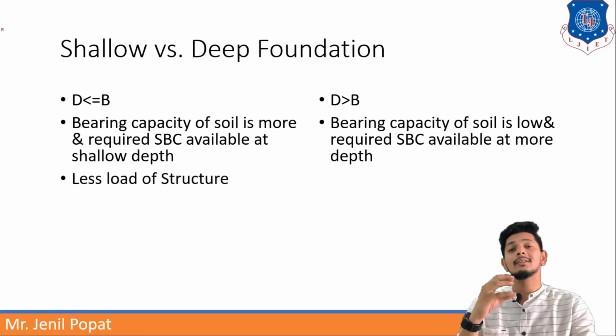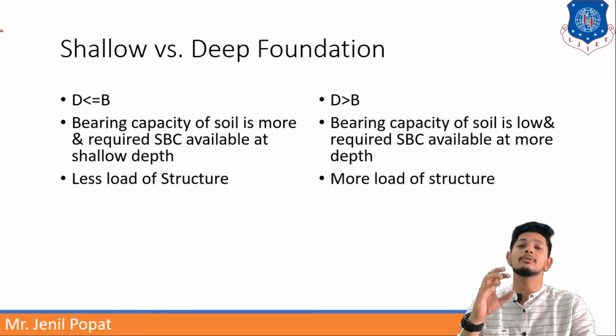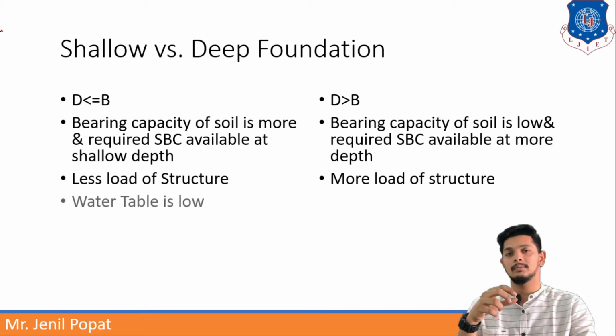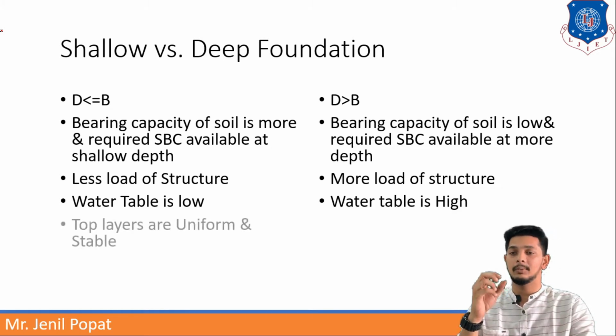If the structure's weight is less, then you will provide a shallow foundation. If the load of the structure is higher, then you will provide a deep foundation so that the foundation can take the load. When the water table is low, you will provide a shallow foundation, whereas if the water table is high, you have to provide a deep foundation so that the strength will be adequate.